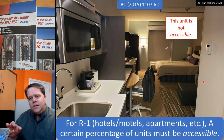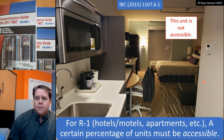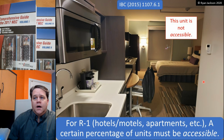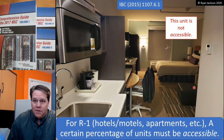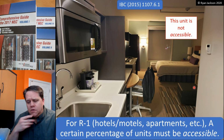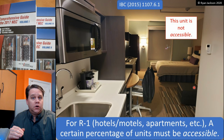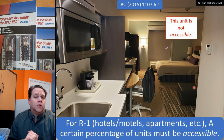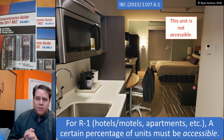Going in a little bit deeper, we have occupancy type R1, which is hotels, motels, and apartments. In other words, not apartments. Hotels and motels. Scratch the apartments. A certain percentage of units must be accessible. So you've probably all been in hotels where you've got the accessible units with the roll-in shower and everything else. Those have to be full-blown accessible. The other units do not. So R1 is actually pretty easy.